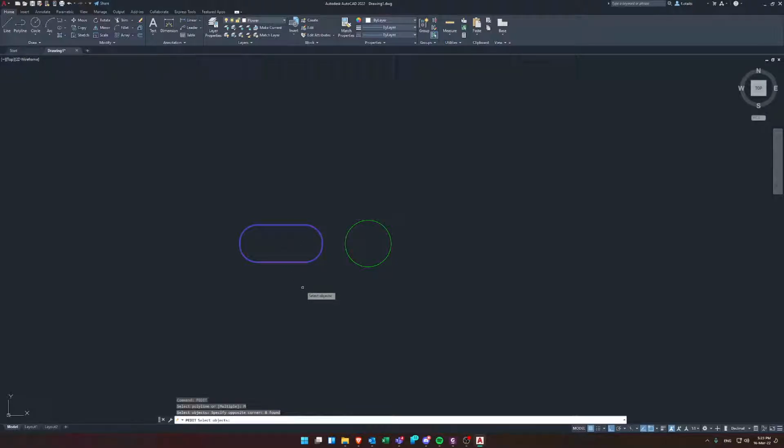Yeah, let's choose all of it and enter. Yes, convert it to polyline. And now I can change the width. The width on the paper is 0.01. And once I'm done, I'm not gonna press on close. No, I'm gonna press on escape on the keyboard.